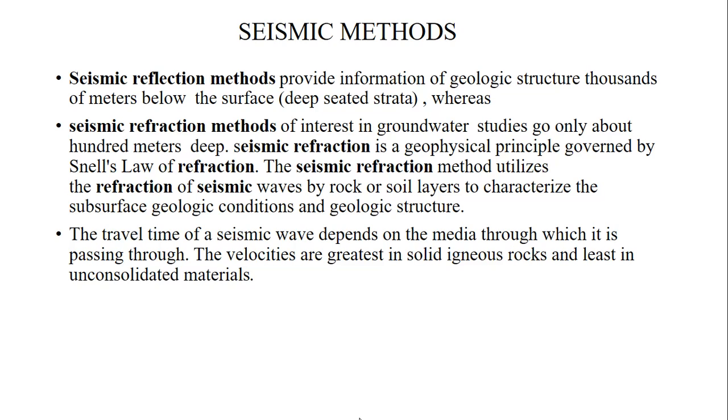Seismic refraction is a geophysical principle governed by Snell's law of refraction. The seismic refraction method utilizes the refraction of seismic waves by rocks or soil layers to characterize the subsurface geological conditions and structures. The travel time of seismic waves depends on the media through which they pass. The velocities are greatest in solid igneous rocks and least in unconsolidated material. This phenomenon is used in the seismic refraction method.